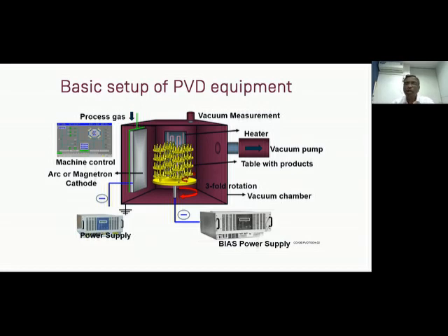So what we do is give a negative potential to the tools. With this negative potential, these positively charged ions get attracted towards the negative potential surface, and they start bombarding at the initial stage. Once the bombardment is done, and with appropriate adjustment of the different voltages, we start developing the coating on the surface. With this, we can do coatings of 1 micron to 12 micron, 15 micron, depending on the application requirement.